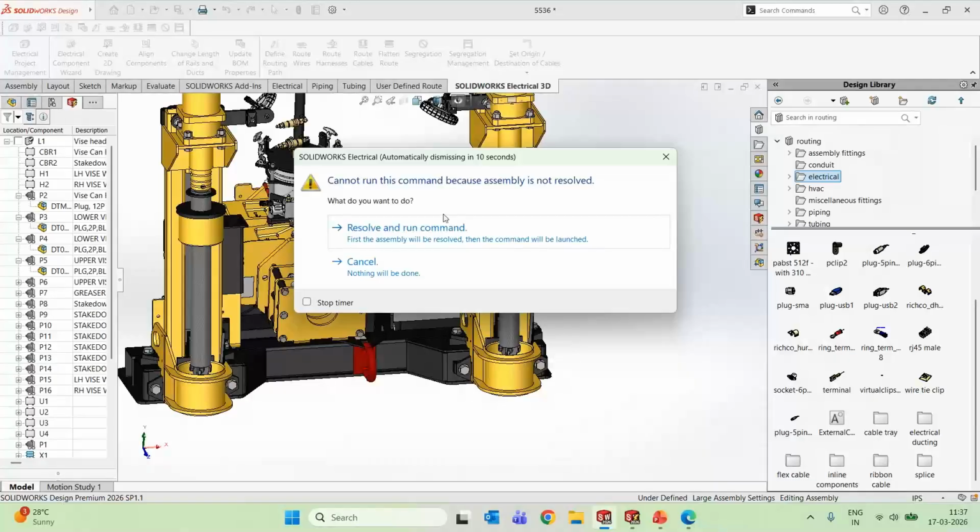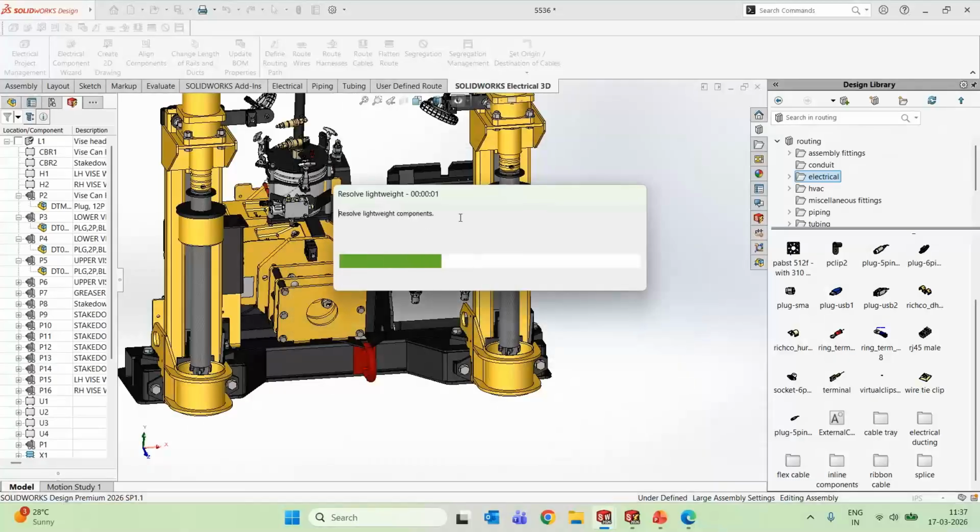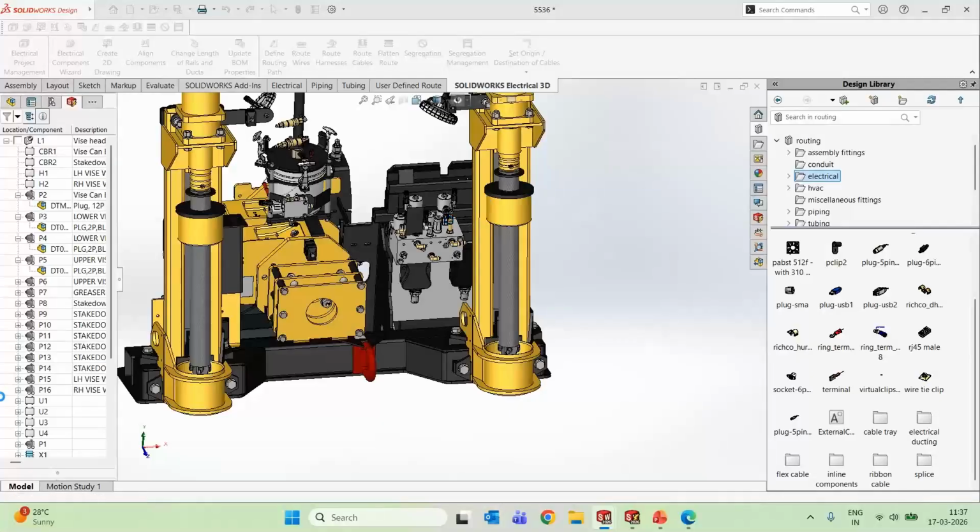So what happens is we will be able to go and get the data from the 2D. Why are we getting the data from the 2D? Because we are able to identify that in 2D there is a connector with some connection point, and in that connection point there is some wire running. Through that data only, the 3D electrical software is fetching the information and will do the wiring accordingly.